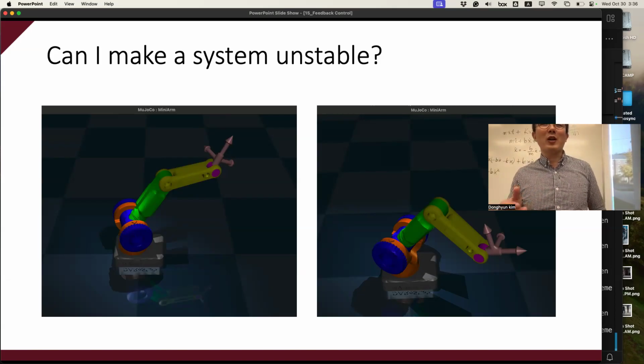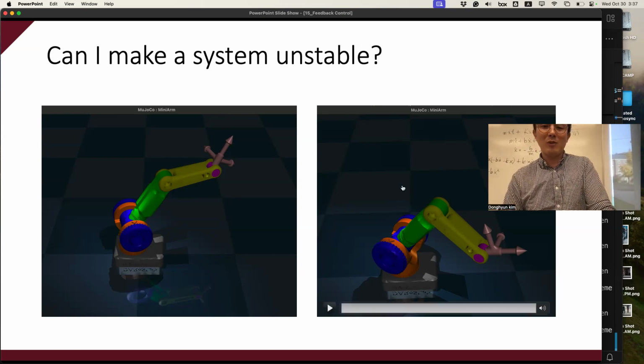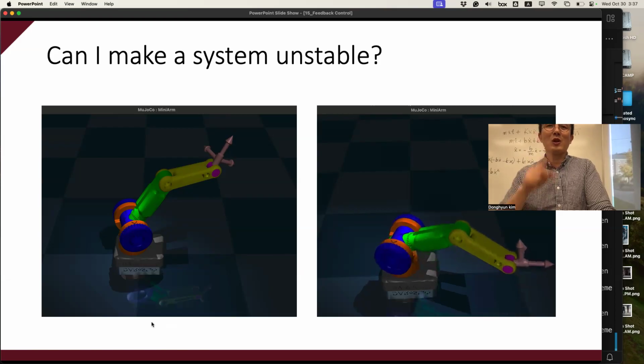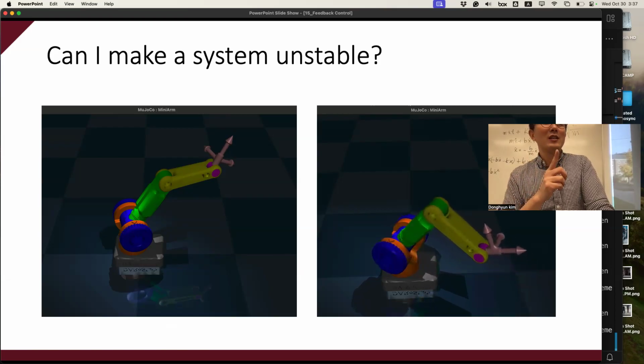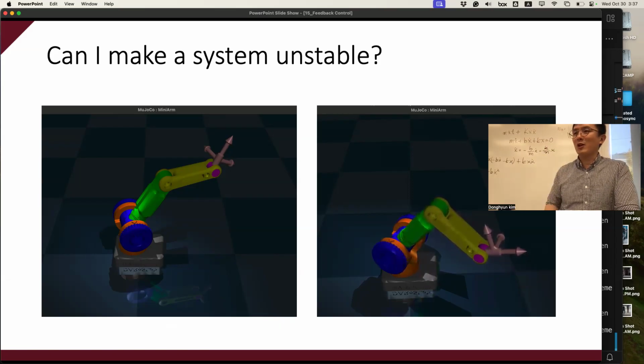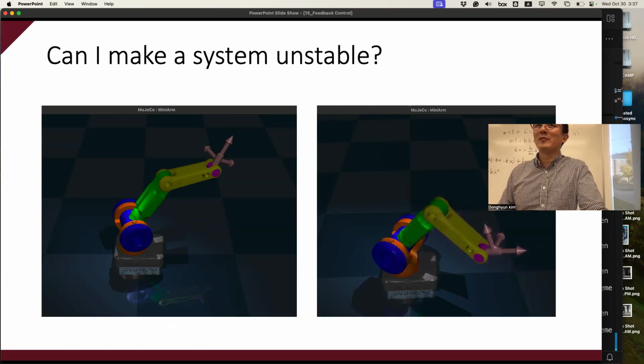So that's why when I first set up the dynamic simulation, this behavior is using only 1 as the KD. When you increase the KD, even in your simulation, you have to be careful because it can blow out the system. And in the actual world, it's even worse because you're going to see all the noise in the velocity signal.